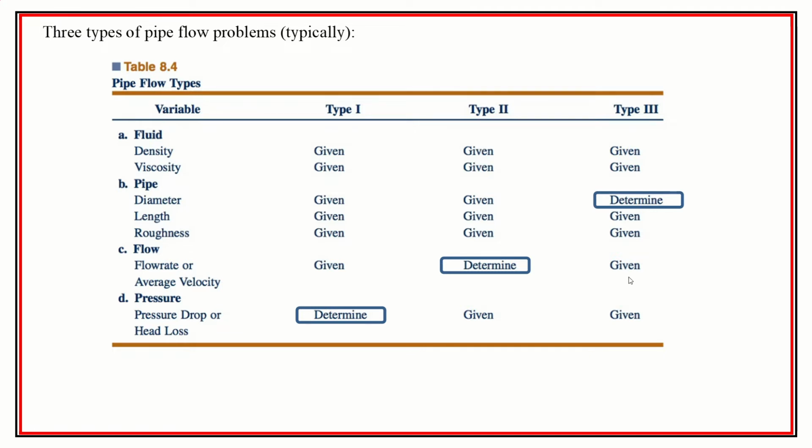So we would know what the flow is and maybe what the pump power is going to be, and we want to determine what size diameter of pipe we need to be able to achieve those goals. And once again, this can be done by creating a spreadsheet in an analysis situation and turning it into a design tool by using GoalSeek.